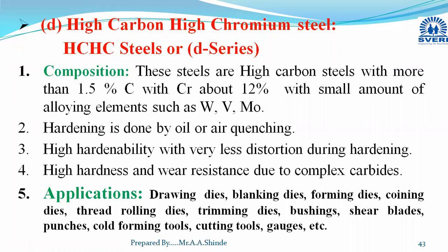Okay, so the main characteristic here is high hardness and high wear resistance due to the presence of complex carbides, and they provide this high hardness up to a temperature range of 500 degrees Celsius. Hence, we can use these HCHC steels for different applications, like in manufacturing of drawing dies, blanking dies, and forming